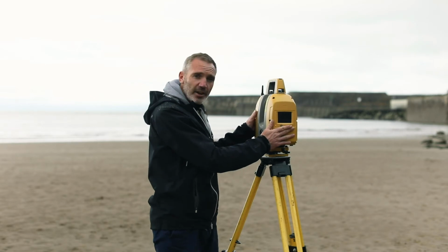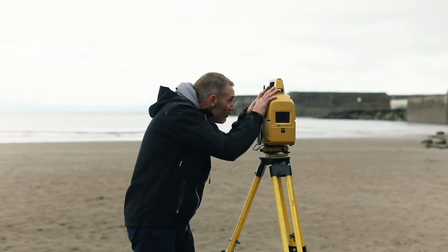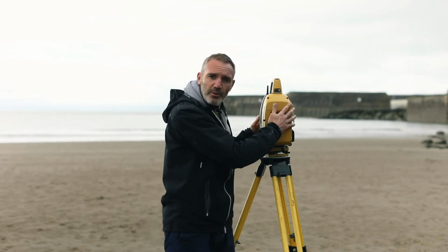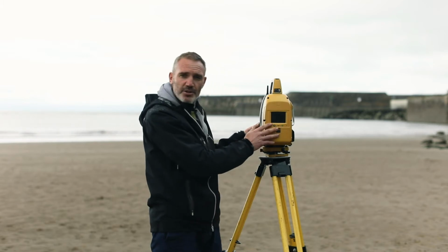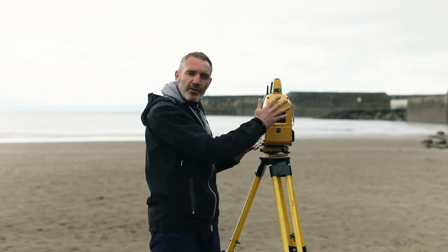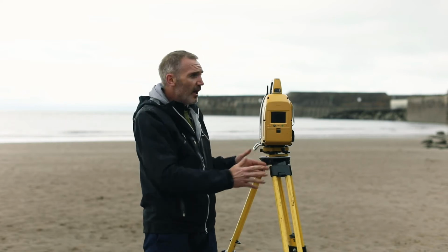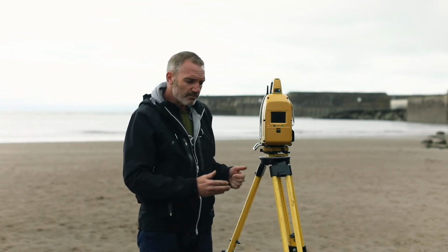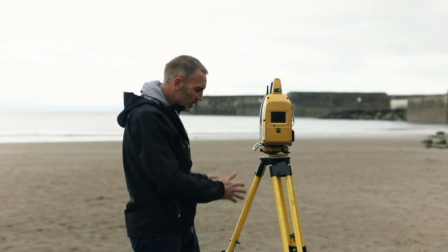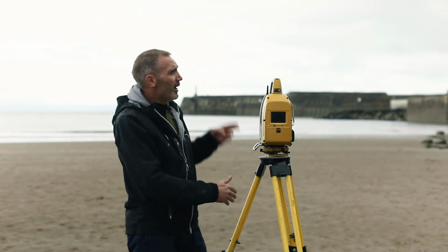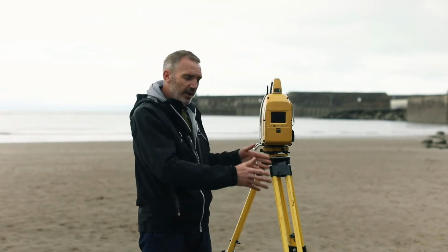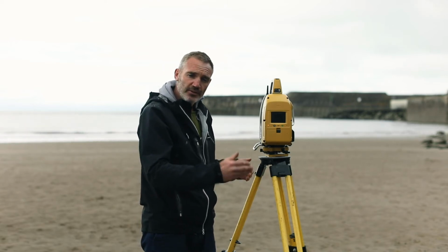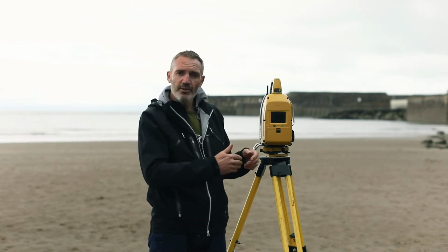That could be another surveyor with a reflective target over another known survey peg. Just like a total station, we rotate the instrument and roughly sight onto the other point, and we've got the camera to help us in that process. Then we simply take a measurement, and it will measure the angle and the distance to that other point. That will then fix the position and the orientation of the scan in Ordnance Survey National Grid coordinates. What that means is when I move to another position, again over a known point, and sight onto another known target, we get the exact coordinate of that point as well. That's another way of joining together successive scans, not necessarily with the need for overlap.